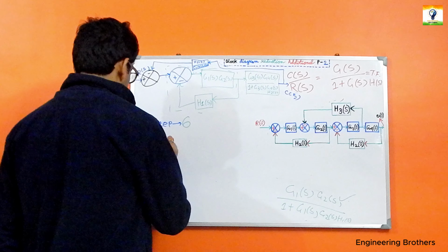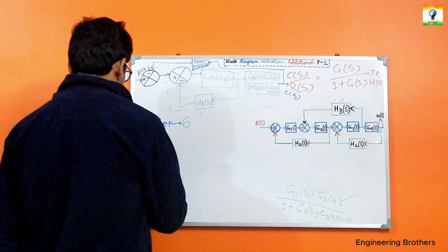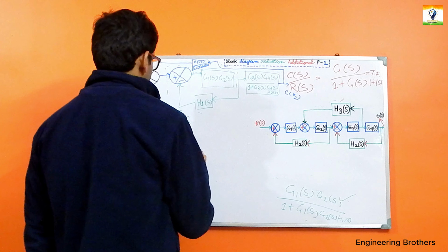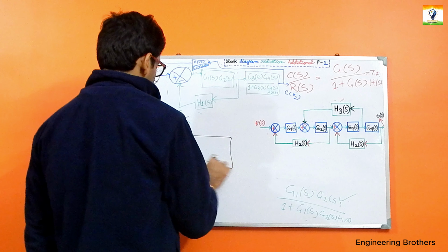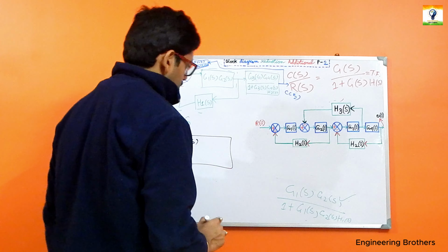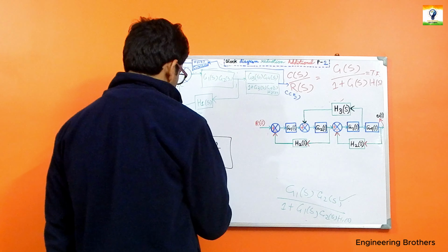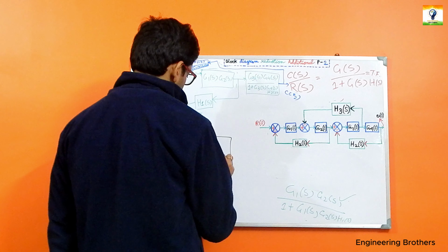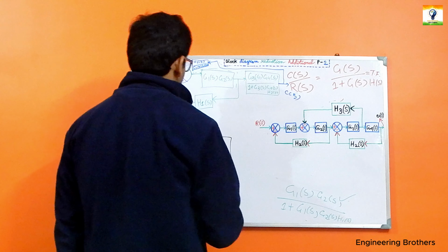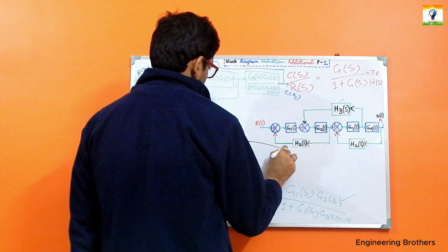Ultimately we have got this is plus, this is minus, this one is our RS, and quite naturally after we have considered that formulation, the given block diagram looks like this one, which is our G1s G2s divided by 1 plus G1s G2s H1s. This is our considered block diagram over here,